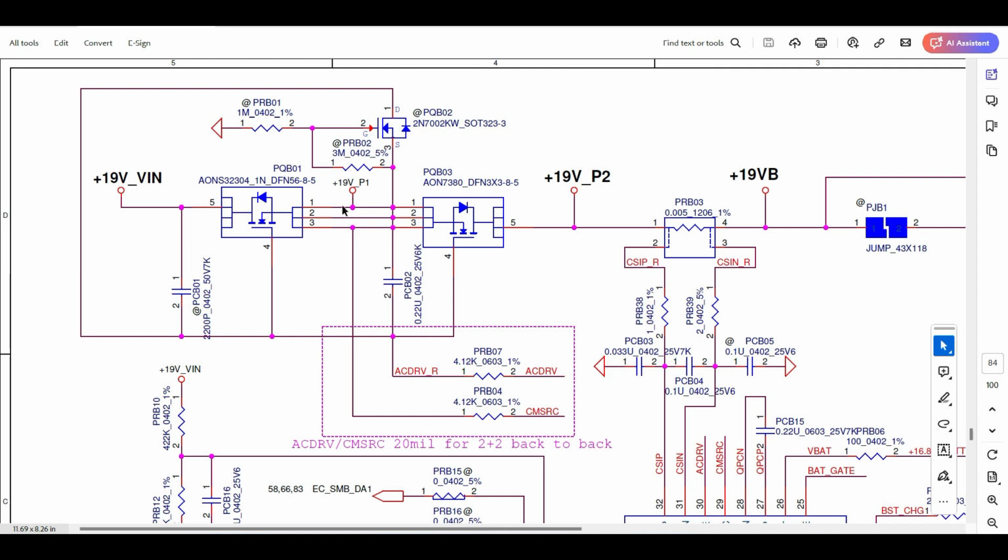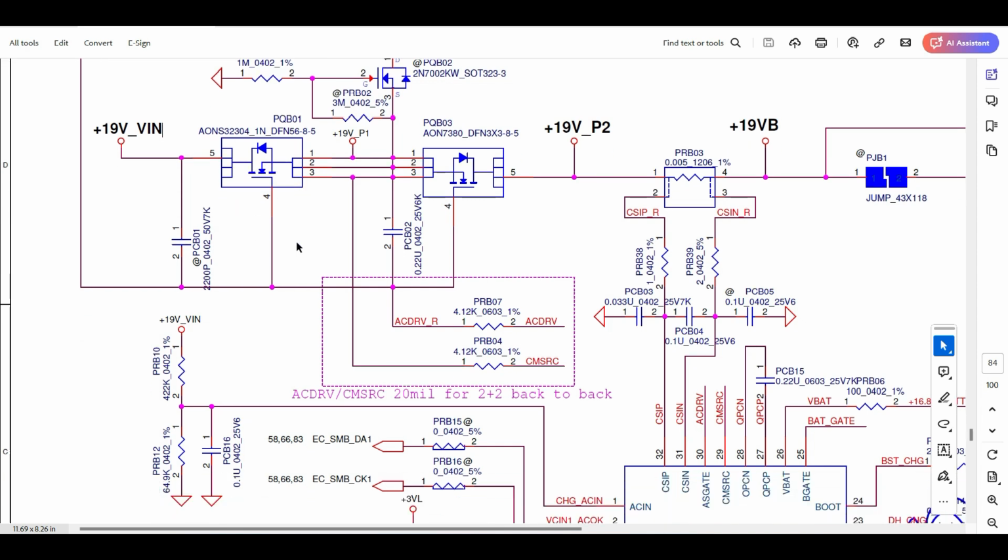So it should be greater than the drain voltage. So here it's 19 volts, here approximately 24 to 25 volts it will get, or more than that, or a little bit less than that also. Once it receives it, next see here AC drive, through this IC it will receive the voltage, and once the gate voltage comes, then it will pass here, and we will get this one.